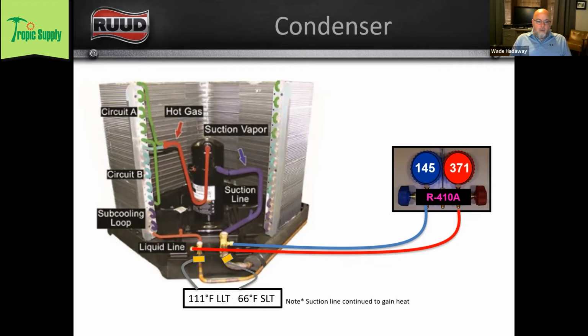And again, if we don't get the temp of the refrigerant over the ambient temperature, we're never going to remove that heat, right? So if you're only checking your superheat here, and yes, I realize that virtually all modern systems have an expansion valve, and we're going to charge a system with an expansion valve using the subcooling method, but it's also important to check superheat and know what's going on with your refrigerant as it leaves your evaporator